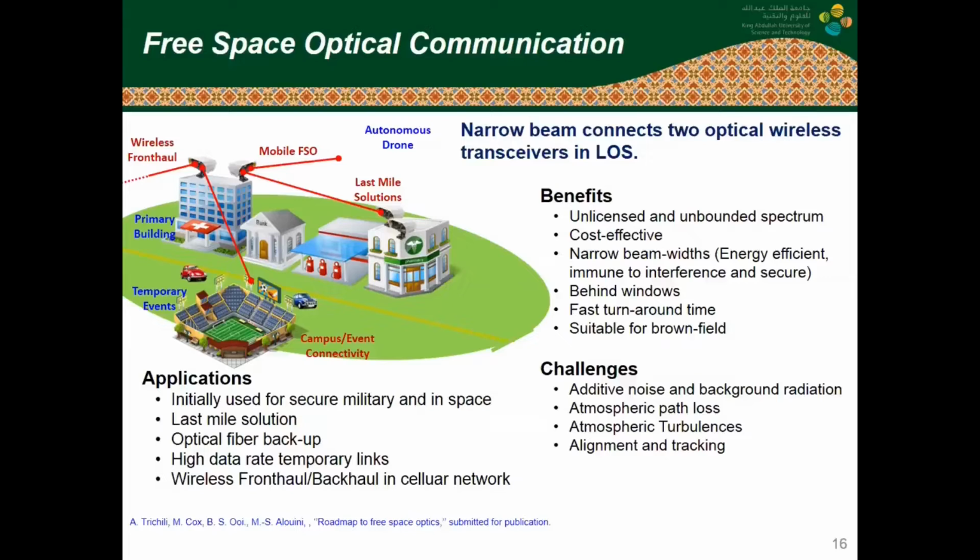And of course, as we talk more and more about 5G and 6G and smaller cells, cells need access points or base stations. These base stations have to be interconnected or connect at least to some kind of backbone. And this connectivity was done traditionally through fiber optics, but when this thing grows, when you start having a lot of these small cells, obviously you want to go to a wireless backhaul solution or a wireless front haul solution.